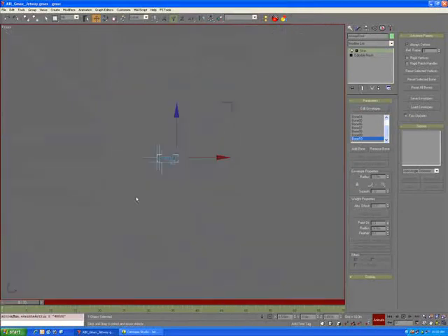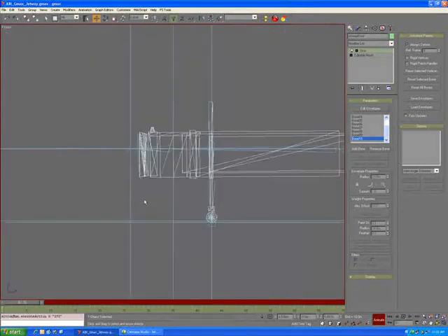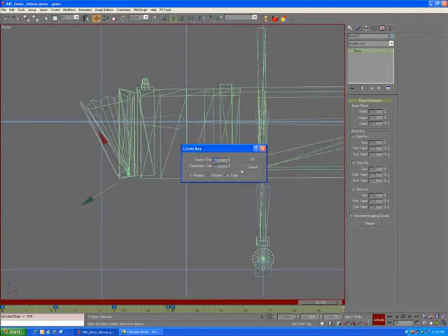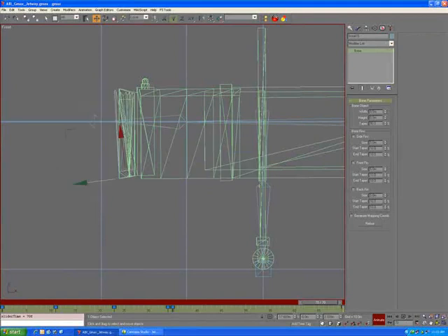Now we want to make sure we have keyframes on this all across the board. So we'll select that bone again and animate. You can just go in and fill in some keyframes to make sure that the pure linear rotation doesn't get optimized. Then set a key on 35, go back to 70 and copy your 0 keyframe to 70. So now you have both an extend and a retract animation. Then we'll fill in a few keyframes on these as well, just to make sure they don't get optimized out.